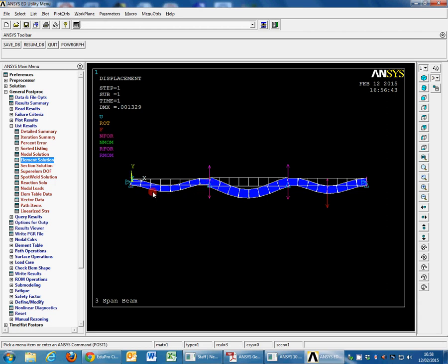And it just so happens that the moments at, let's have a look, think of it this way. Each element has two nodes, I and J. So its lower numbered node is I, its higher numbered node is J. What we want to do is get the moments out for nodes I and J. And the moment at node I resides in a little library accession place called miscellaneous item number 6. The moment at node J resides at miscellaneous item location number 12. So this is how we can plot bending moment diagrams.